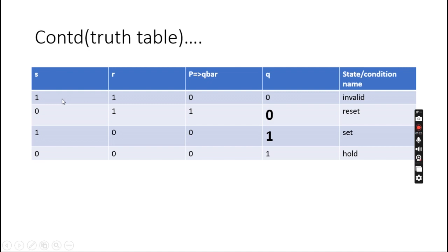Because the reason is, NAND latch will be in invalid state when we apply 0 0. Okay. So if we want to make it valid or useful, we should change any one input. Whenever the inputs are 0 0, even if we feedback output many times, it will maintain the same output. Okay, we cannot go to a valid state from the invalid.